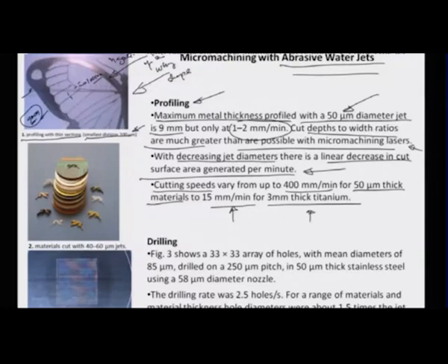But still it does matter at what speed you raster on the surface. As you can see here, the cutting speed is higher, meaning thereby that the depth of cut of the material is lower. One of the reasons of course is the fact that you have less dwell time on a certain area.